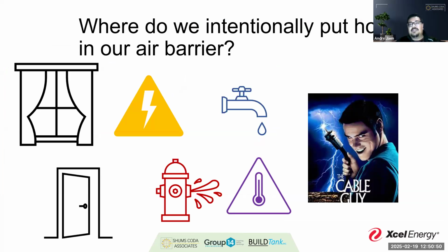I made this slide kind of laughing when I threw in the cable guy thing because they to me were always the most notorious ones for taking like a hammer to make a hole for a quarter-inch cable or using a 4-inch hole saw for a 1/2 inch data cable or something like that. And so I had a guy that ran like 6 holes through every draft stop in a multifamily building on me doing exactly that right before final, and the super was just coming unglued over him. But I mean, these are all the examples of all the places where we intentionally put holes in an otherwise air-sealed, airtight box that we've been trying to make. So we spend so much time trying to build a comprehensive thermal envelope.